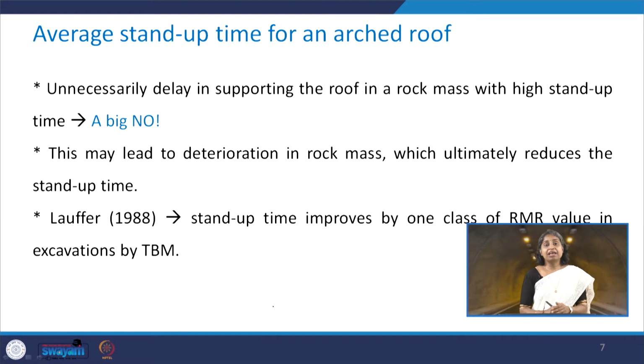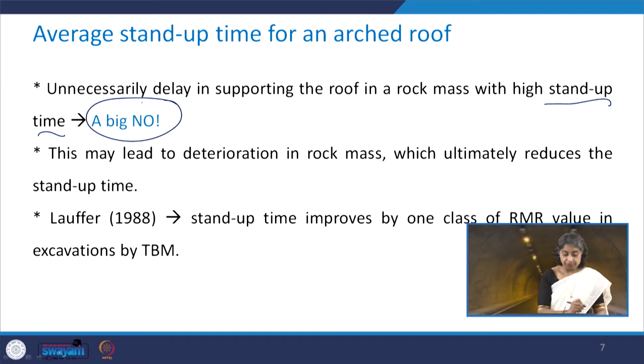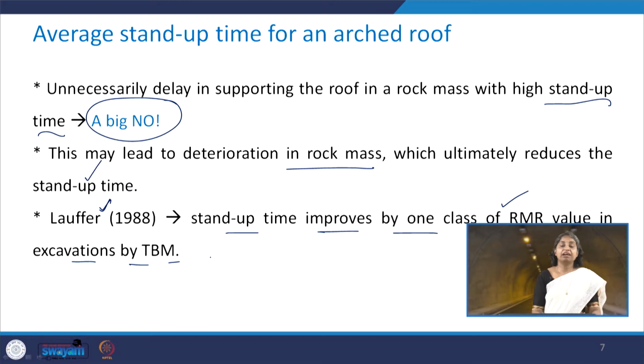As I mentioned, there should not be unnecessary delay in supporting the roof in a rock mass, even though it has high stand up time. So this is a big no. This may lead to deterioration in the rock mass, which ultimately reduces the stand up time. What this research worker mentioned is that stand up time improves by one class of RMR value in the excavations which were made by tunnel boring machines.